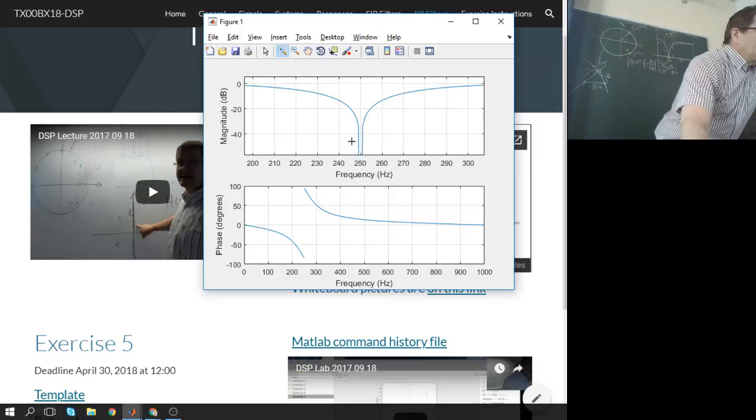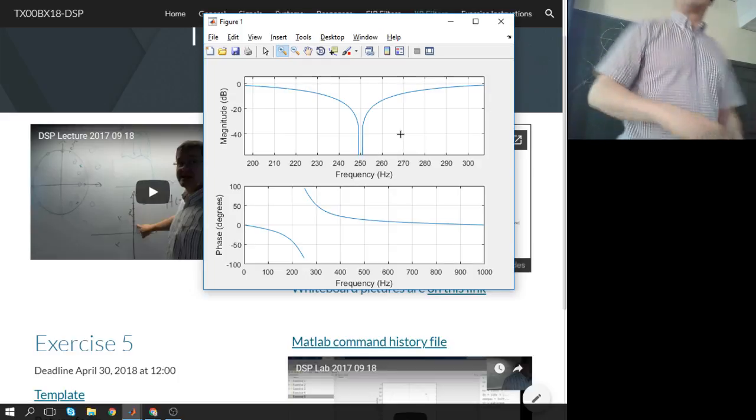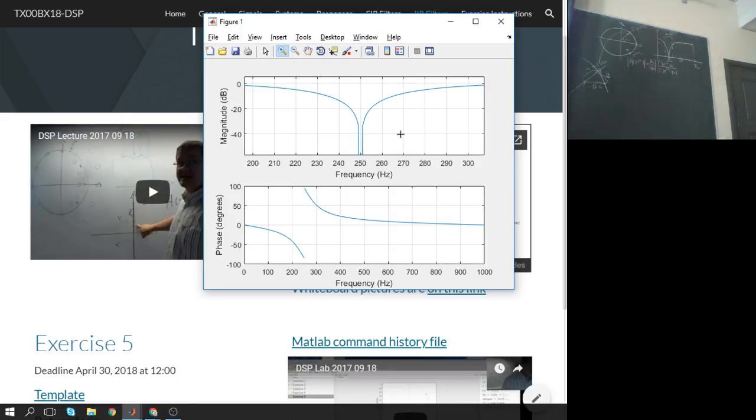If your sampling rate is not exactly correct, for example you have even 1% difference, 1% difference in this scale would mean a 10 hertz change in the real frequency, meaning that you are rapidly losing the whole idea of having this as the filter if you don't match this frequency exactly.